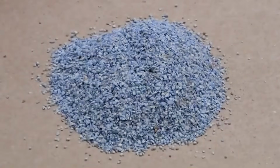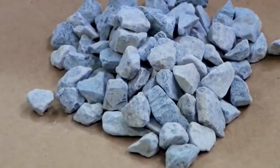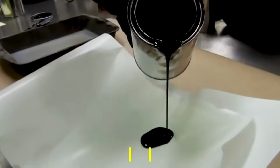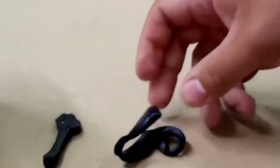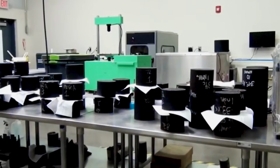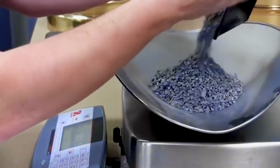Fine aggregates shall pass the 2.36 millimeter sieve and be retained on the 75 micron sieve, consisting of crusher run screenings. An important information is that the natural sand is not allowed as fine aggregate in any asphalt work. Generally, bitumen of grade 80 to 100 is used as the binder in highways. The percentage of binder content shall be determined based on the requirements specified in the contract and the traffic volume. The Marshall test method shall be adopted to determine the optimum binder content.